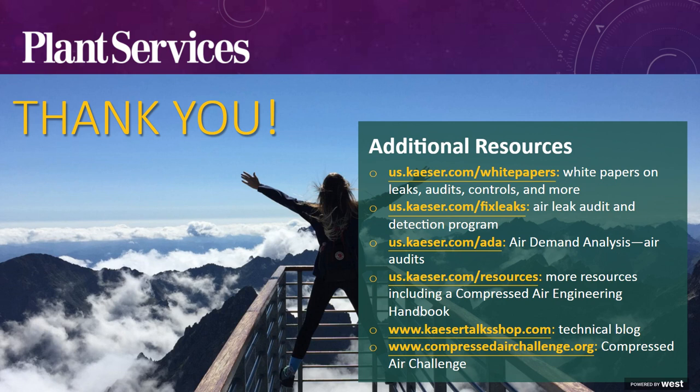I'd say it's always encouraging to work with a plant and set some baselines and help them figure out what the important features are. And like I said, a lot of these new individual controllers and master controllers stream data. So if you do the assessment, you do the audit, and you make the upgrades, the system you've got can stream data. You don't need that extra equipment, and you've got that through your SCADA system, through Modbus or whatever it might be. And you've set tags on, if this happens, do this, send this email, run this report monthly. So you've got a lot of things at your fingertips, which is great.